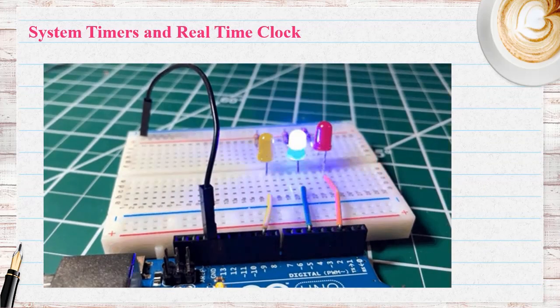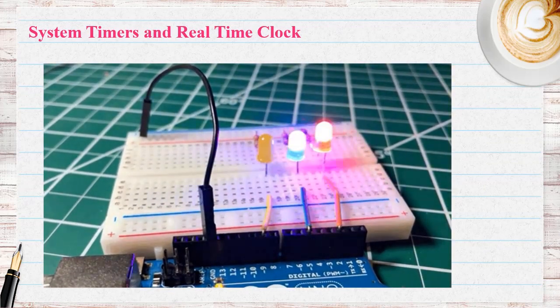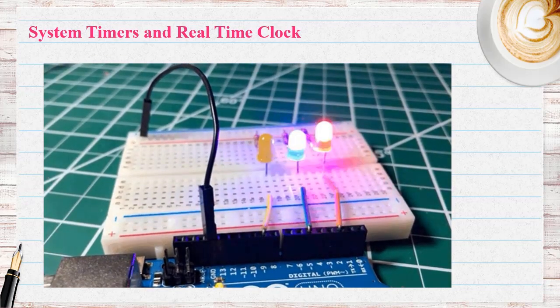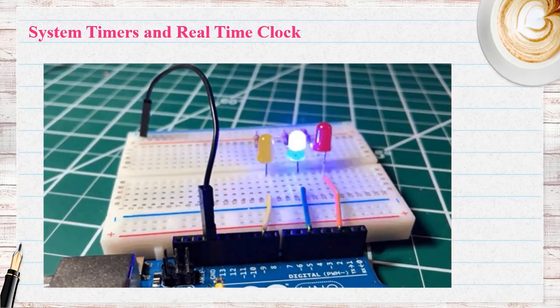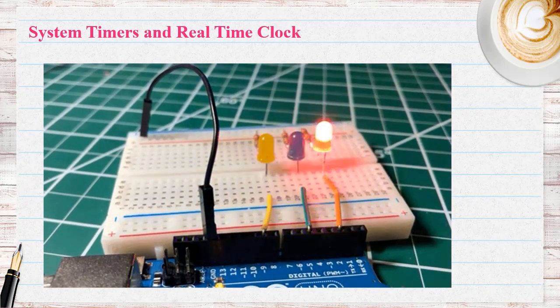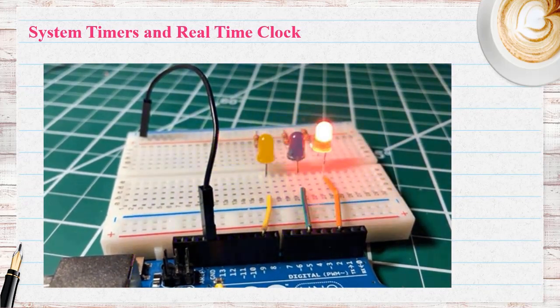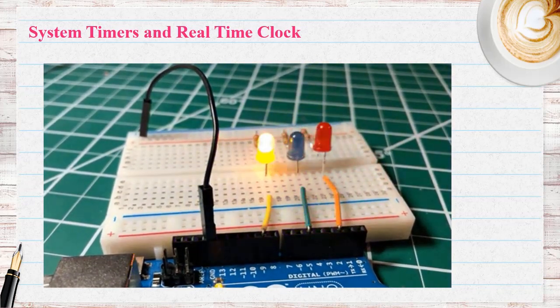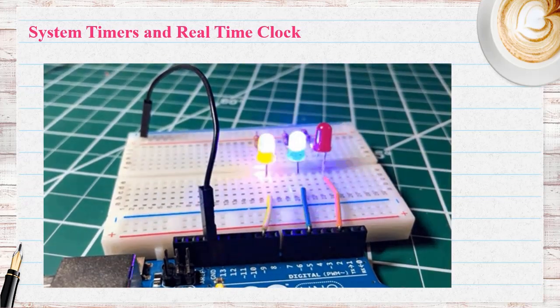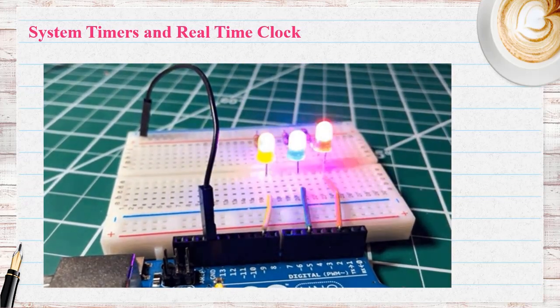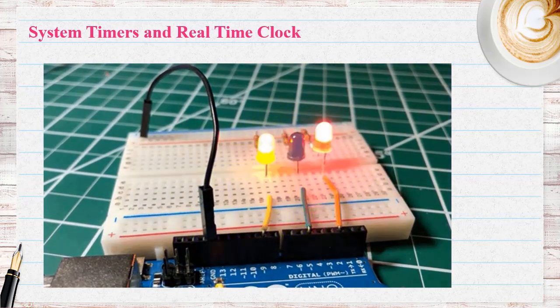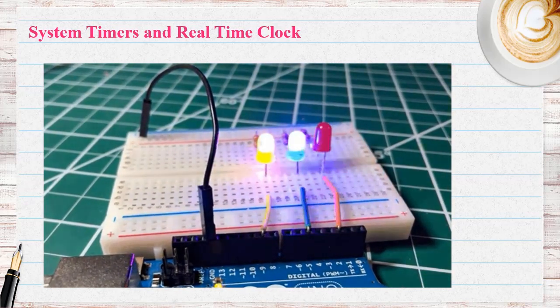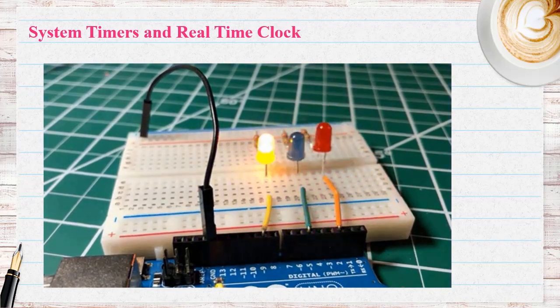If you are working in embedded systems, you must have heard about timers and counters. What are timer and counter? Why do we use timer and counter? What is the difference between timers and counters? In some applications, we need to generate some delay. Like for blinking an LED, we need a delay. For making a square pulse we need a delay. For such kind of application where we need a delay for a specific time interval without affecting the normal code execution, we use timer and counter.